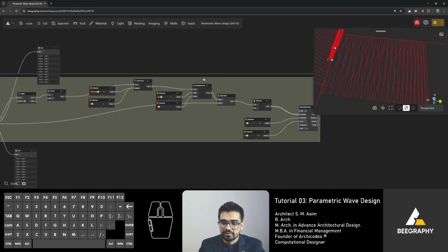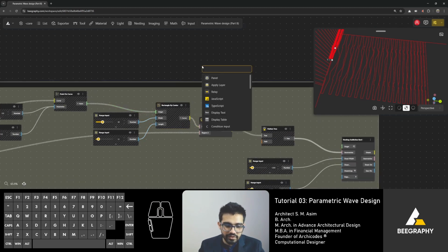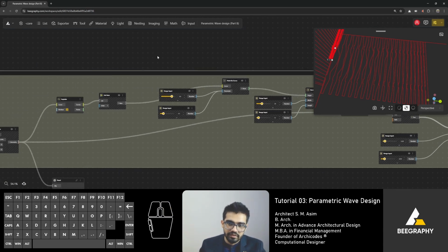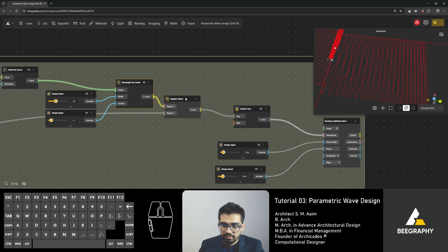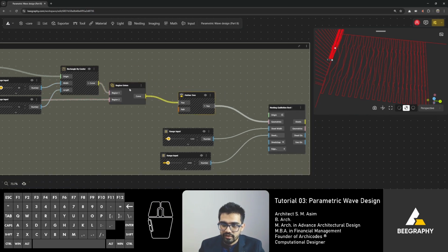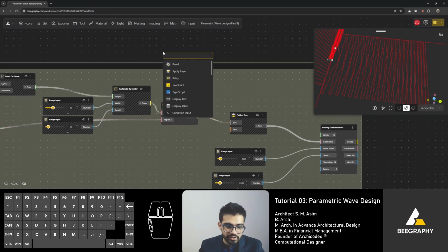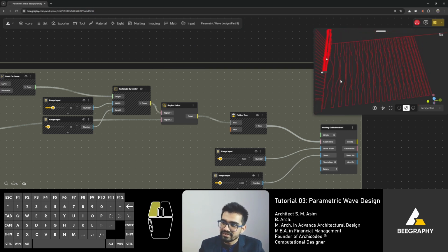All right, so we have got the final outcome. It's just a small glitch. Script is exactly the same. We've got the point on curve, we got the rectangles, everything is nicely branched, and then the region union is done. Sometimes if there is an issue, what you can do is simplify tree, make it go through this, and that will fix it. But in my case, even if I'm not doing it, it's still the same.